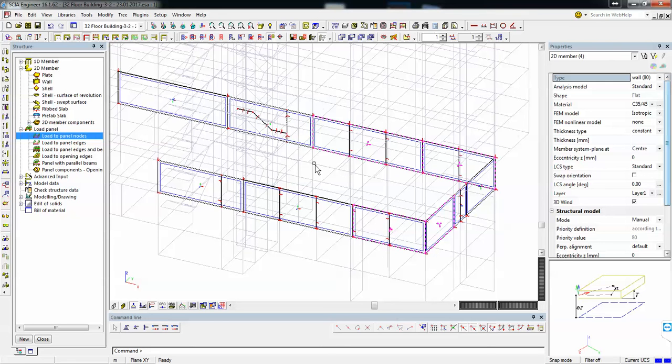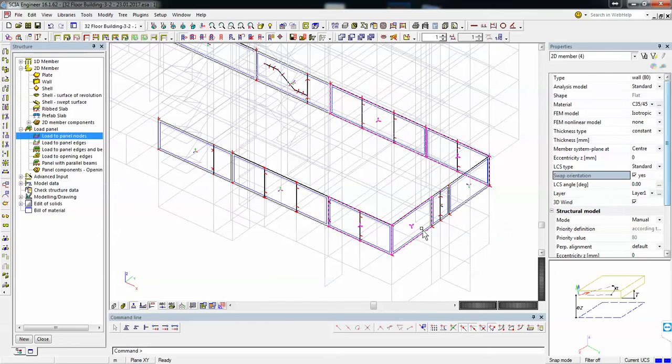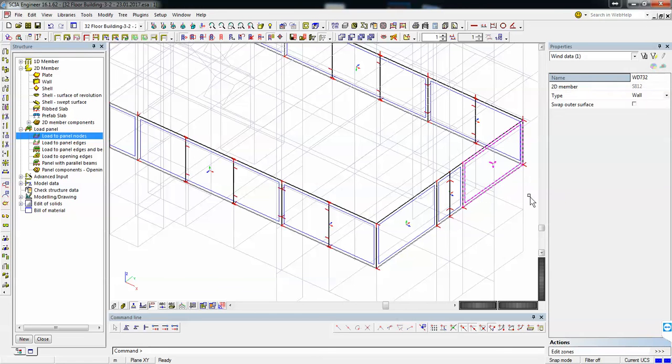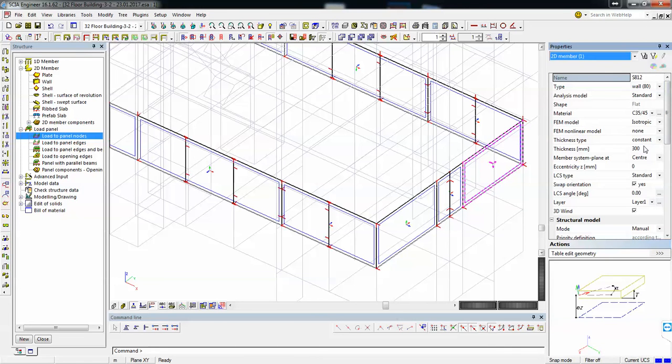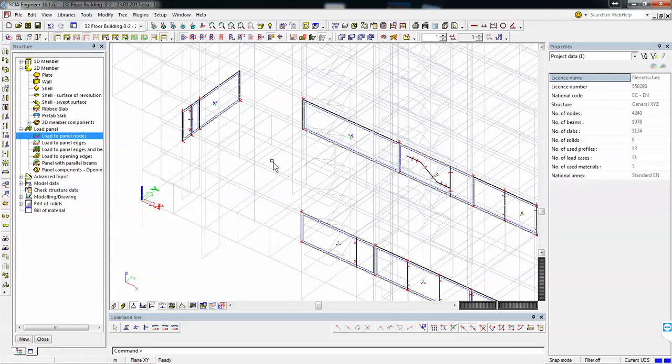So if I change, don't forget to delete the pressure load. You will have to do some changes, because if you already defined the pressure loads but this is the other way, they will change signs, so they won't be correct anymore. All loads are according to the sign of the 2D element. So indeed, that's a good observation. Okay, here we have them.